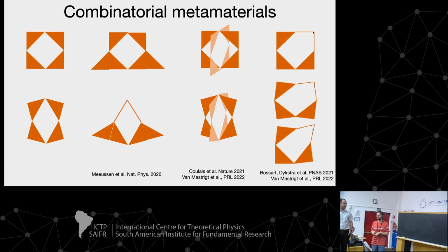Yeah, it does. You have a regime where it stays stuck, and a regime where actually you have a transition wave, a traveling wave that takes you from one state to the other. In fact, we show that the way you can describe this is through a reaction diffusion equation that takes you from one state to the other. And actually, there's some analogy with what you have in nature, like the plant mimosa that also folds. So it's kind of an example of a mechanical wave without inertia, if you wish. And we also show that we can use that to transport objects. So that's actually an interesting thing in itself. Yeah, good question.